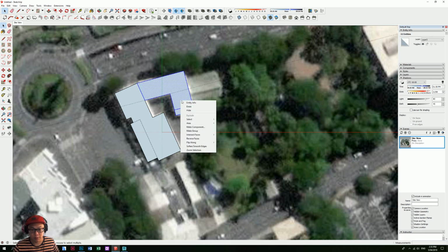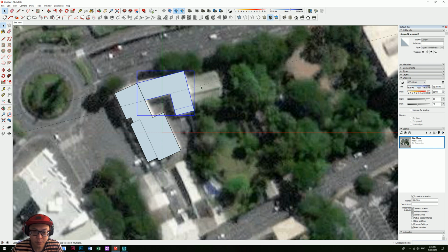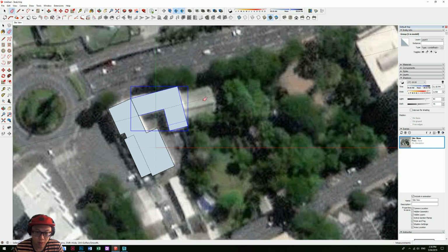Select those, like I think it's double or triple click to select everything. I press E if you want to get the little eraser tool, and I'm gonna take this, so I press T to get that tape measure here to create some guidelines, and I'm gonna roughly put it into place. Here and one here.